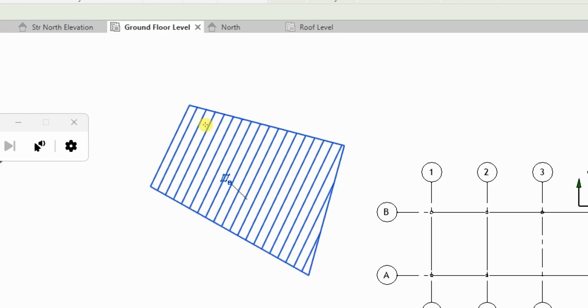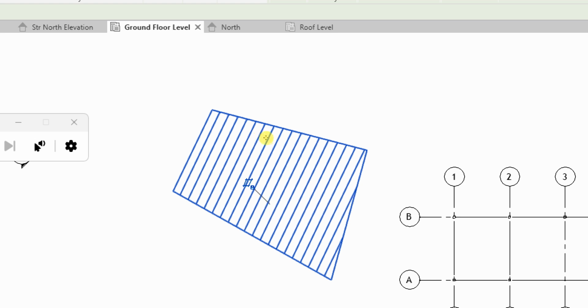600. And I'm saying that especially if you are doing a wooden structure whereby you are going to use a lot of ceiling joists or ceiling wooden members. If you want to create your ceiling in your structure and you want to show your ceiling members, this beam system comes in handy. If you want to create your purlins on the roof, this beam system comes in handy.